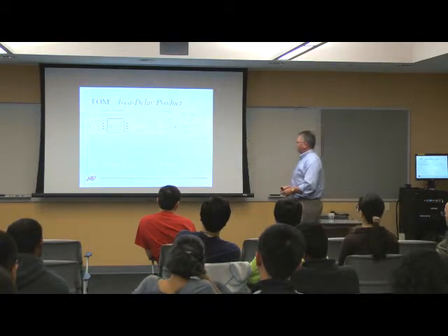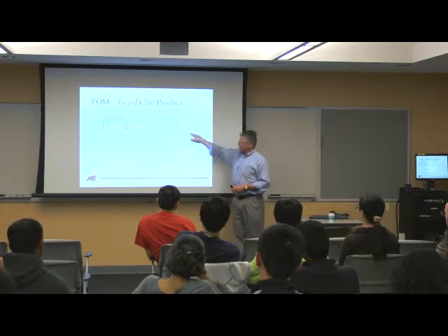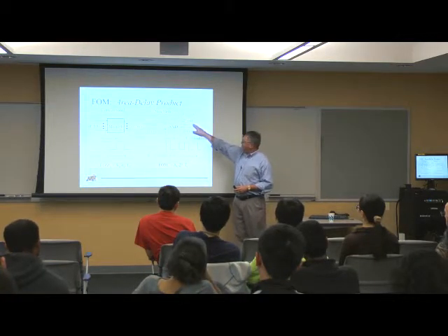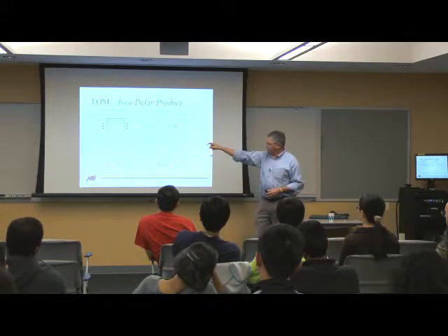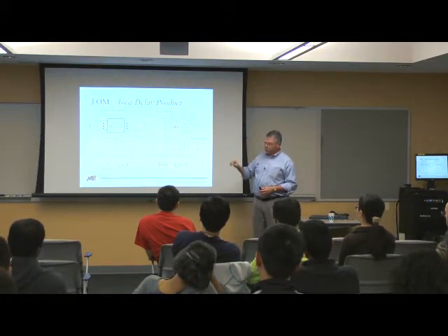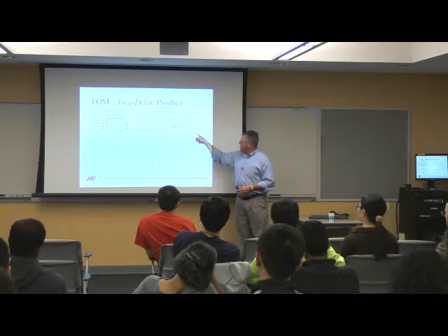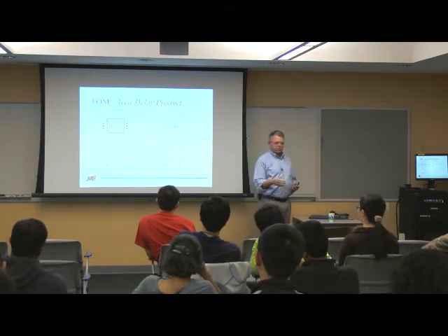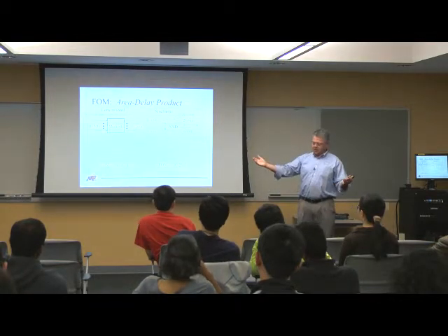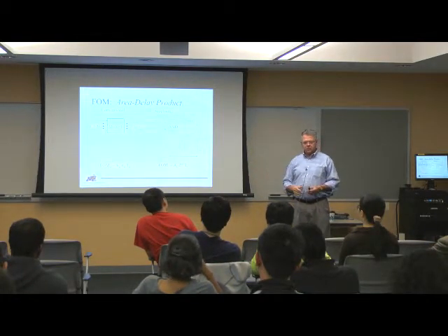Key difference now, though, is that I'm doing this in a bit serial fashion. So if I have m bits of resolution, so 2 to the m is the width of the multiplication over there, then it's going to be 2 to the m cycles to get through here. So if I'm doing a 10-bit resolution, 2 to the 10th is now suddenly 1,024 bits to get through there.